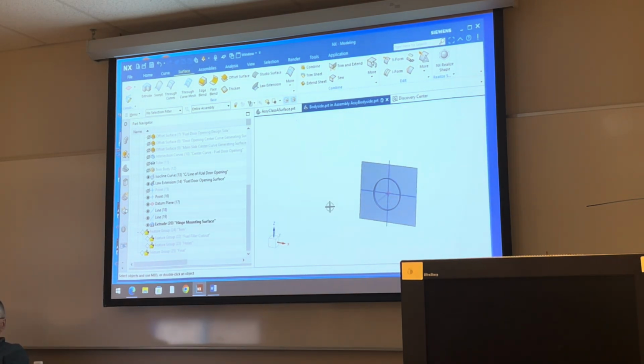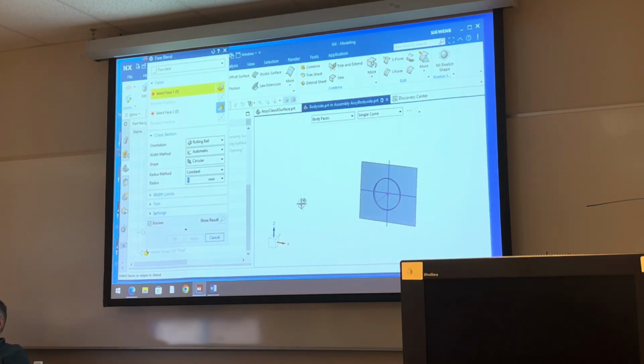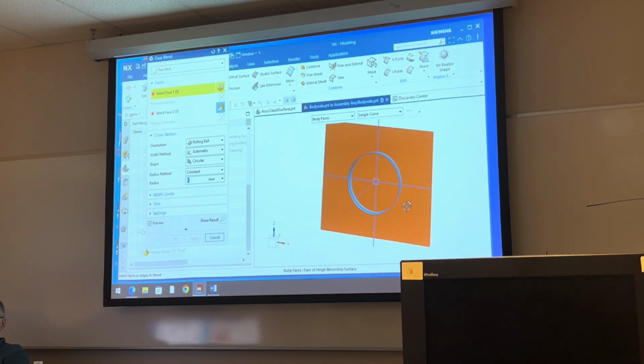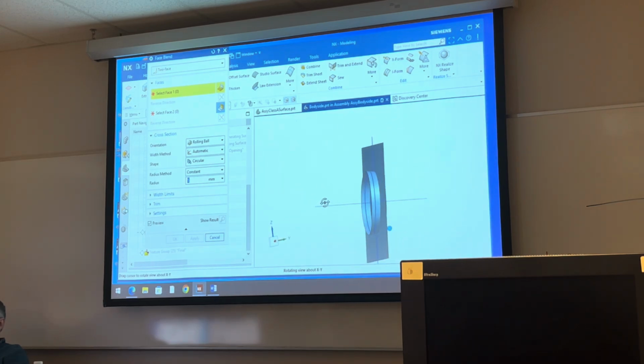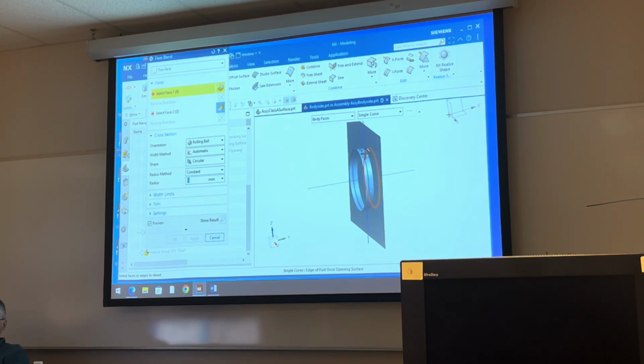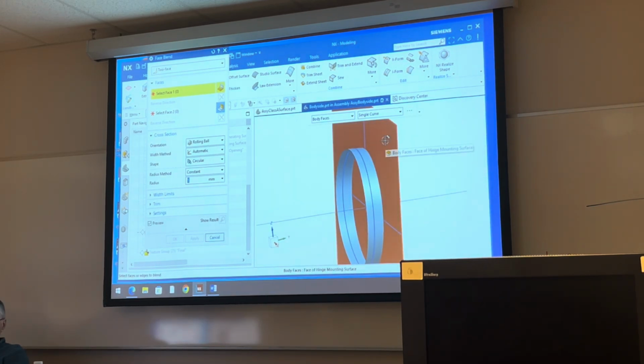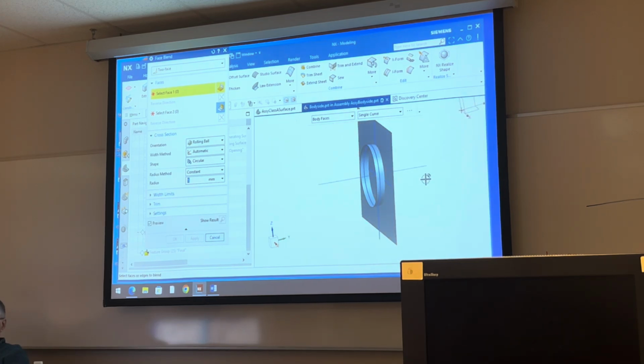Now, I got two more steps, just a couple of fillets, all right? So it says create a face blend between, here's face blend, I'm still in surface tab, the fuel door opening surface. So I'm starting my pocket, which is the fuel door opening. I'm starting it by taking that cone that we made and the back wall and putting them together first.